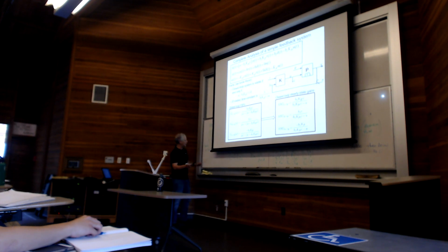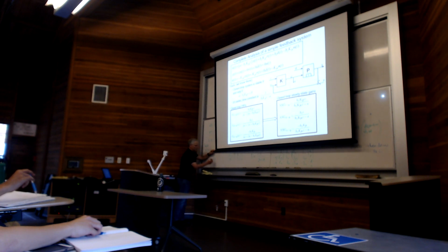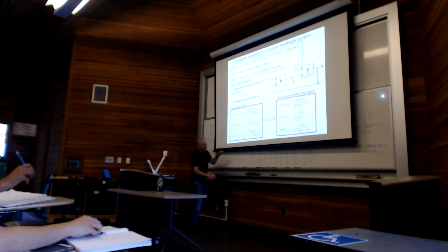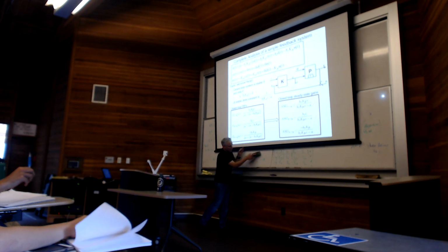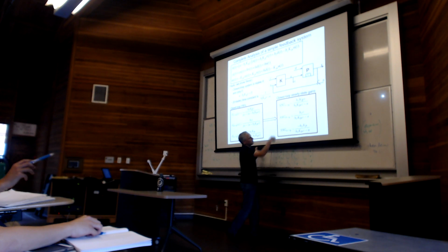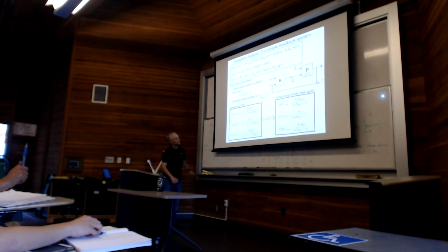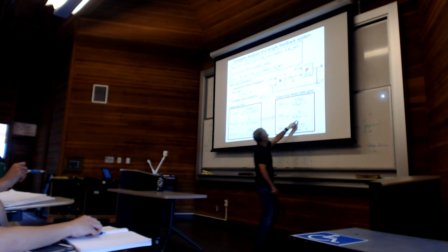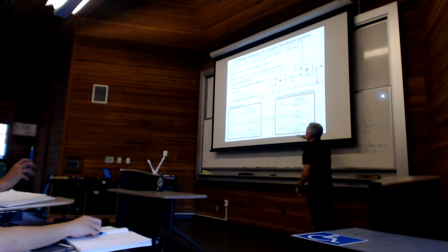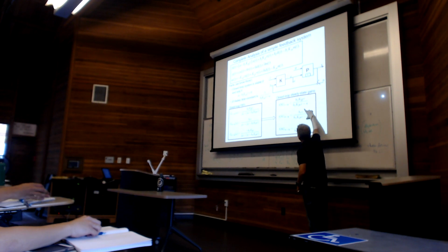What do I set omega equal to? What sine wave is constant? Omega equal 0, right? At omega equals 0, you just get negative b over a or negative cb over a, just like we were used to. So here I've set those. Now you can get a sense of what you might want to do. You might want to pick KFB to make the steady state gain from d to y smaller than some number. You want to make sure that a constant disturbance doesn't have much effect on y, so I can pick KFB to make this small enough.